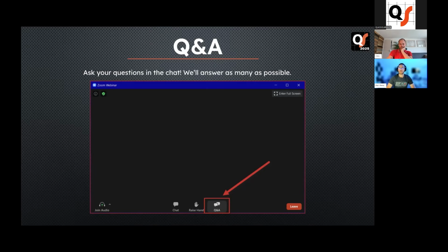Yeah. So basically about QuickSurface Pro, let's see, have the knowledge and practice on how QuickSurface works. Recently received a request to reverse engineer a car door handle. Did scanning, prep, STL, entered into QuickSurface Pro and did all of the surfacing, showed up with a large number of surface patches, saved it as a STEP, sent it to the customer. He replied saying there are too many surfaces for him to work with.